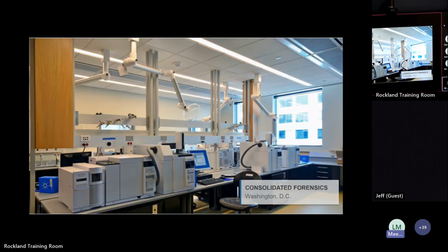All right, so this was a load-driven lab. You can see a lot of the equipment throughout the space, no fume hoods in view. There's some modularity or flexibility in terms of where you can place the chilled beams, but most critically, obviously, you don't want any collisions of the airstreams to have discomfort, but also the fume hood velocities. So just making sure that if you have fume hoods, that the discharge pattern is not going across that fume hood, because that's critical. So this being a load-driven lab, no fume hoods.